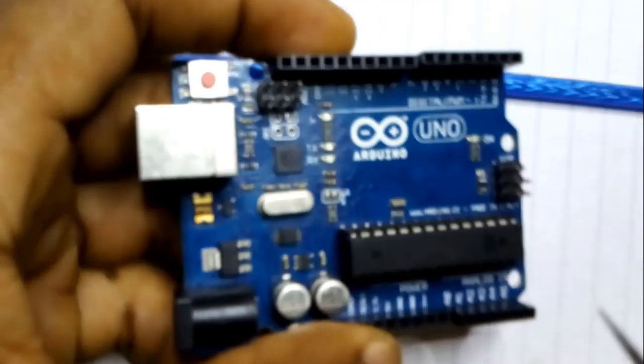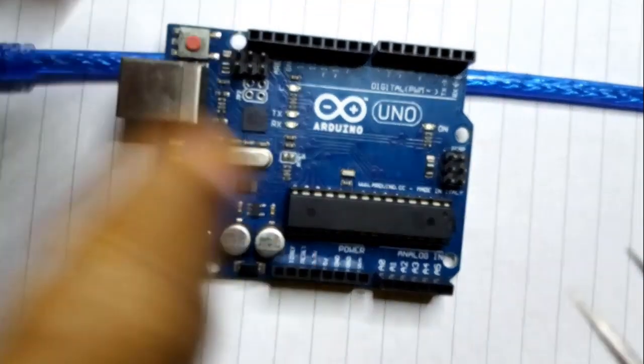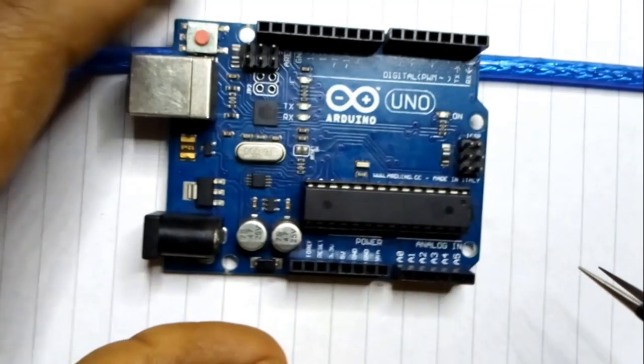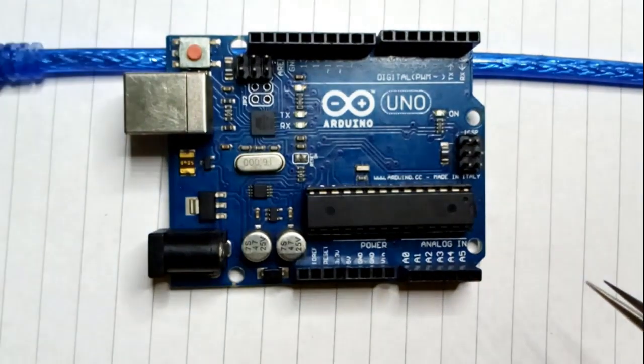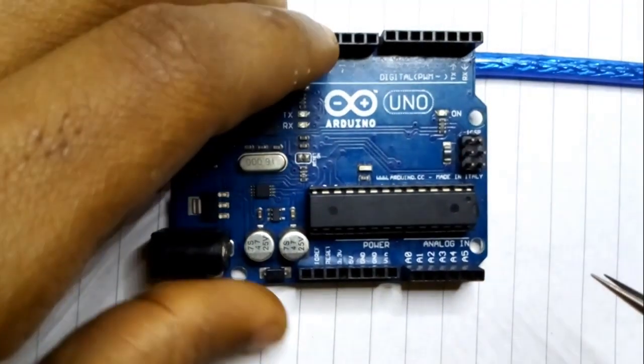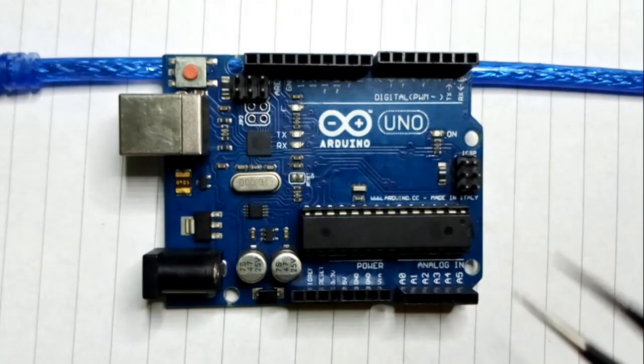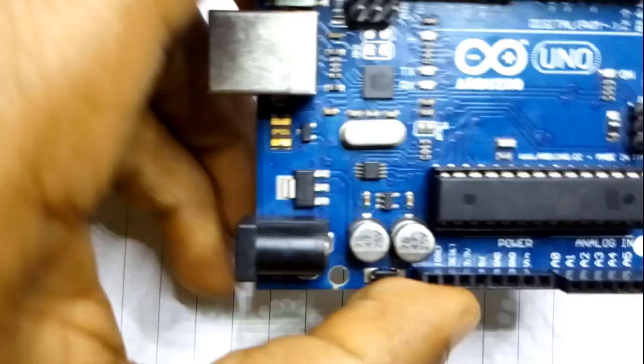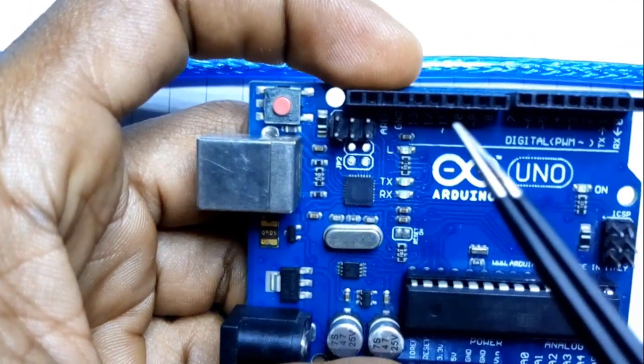However, one thing that you should know is that this EEPROM has a maximum write cycle of about 100,000. This means that erasing and rewriting the EEPROM this number of times will make it unstable. So if you are using the EEPROM for data persistence, you have to be very careful how many times you write and erase.